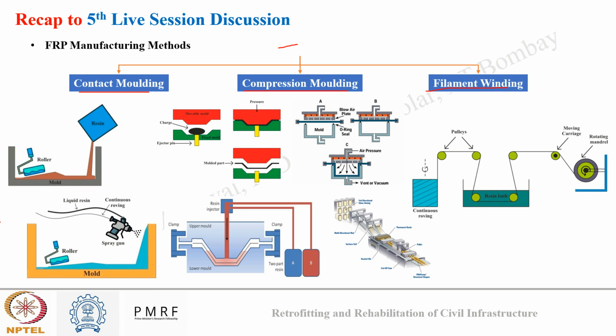In compression molding method, we saw match die molding, forming method employing gas pressure, closed mold molding employing low pressure, and pultrusion forming. The basic idea behind all these was pressing and squeezing a deformable material between two halves of a heated mold or a feed material, and its subsequent transformation into the molded part after cooling and curing.